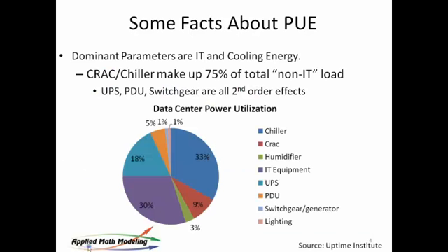But what's going on with PUE is that because it's total facility power in the numerator, the dominant characteristic of that numerator, besides the IT equipment, is the CRAC, chiller, and heat pump. We've seen this a number of times, Liz, where it's really all about this stuff. The other components are modest in comparison and can, for the most part, be ignored.